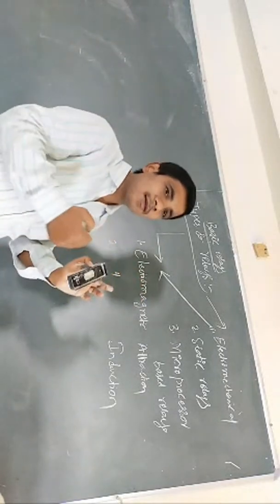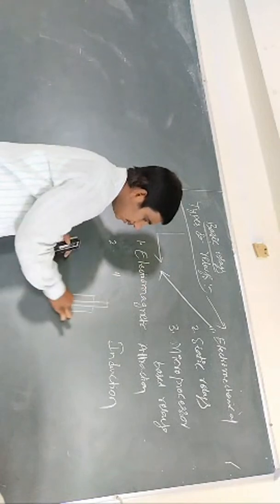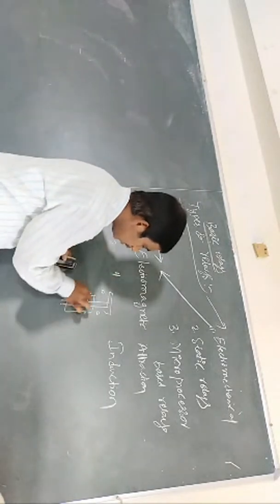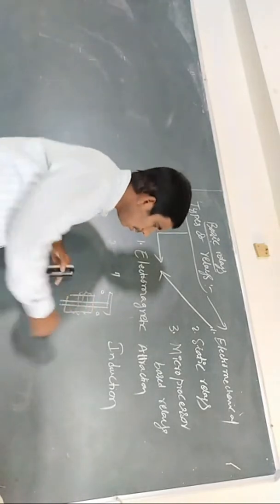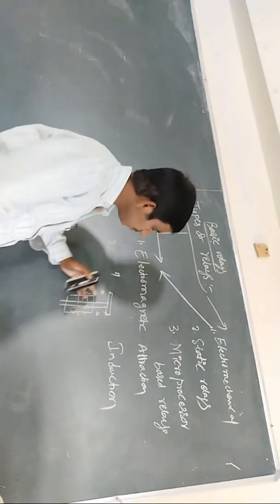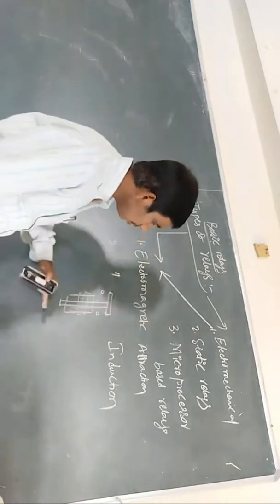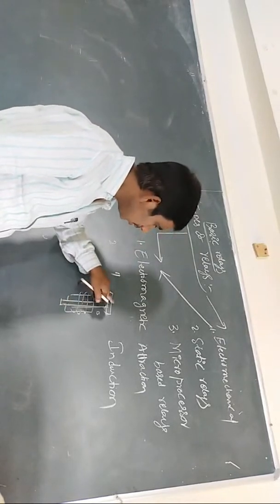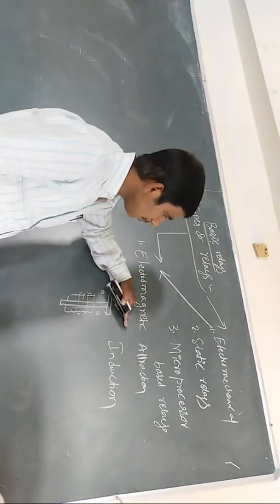The electromagnet attracts the plunger. Previously we told that it has a coil, and a plunger will move inside. This plunger closes the circuit, as you were told in the last class. The coil consists of a number of turns. Whenever fault current reaches maximum, maximum flux will be produced. Due to this, it acts as an electromagnet. It moves downwards. That is the electromagnetic attraction relay. It attracts the plunger or armature. The moving armature is attracted towards the coil.